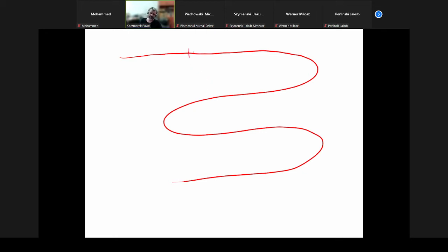We can make a lot of Bragg gratings in different places. Every Bragg grating can be designed for slightly different wavelengths. More or less like this. We are putting some wideband spectra signal into such a structure, and of course every one of these Bragg gratings will reflect different wavelengths, lambda 1, lambda 2, and so on to lambda n.